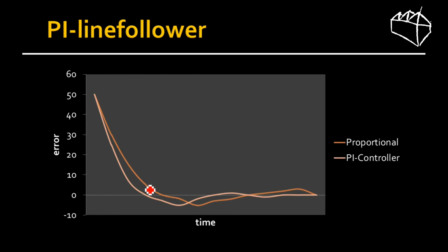So what your robot would do now is it should actually drive forward, but because of the integral, if you switch it badly, your integral will be like 500 or anything, and it will push the robot further to this side, because it has thought, well, the robot was too long on this side, so it will have to push an extra bit more.